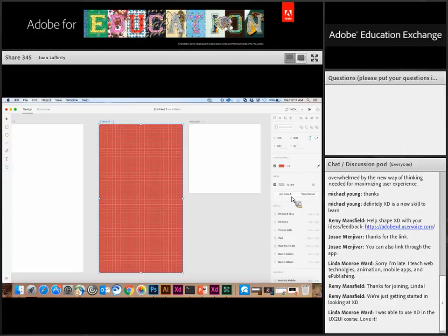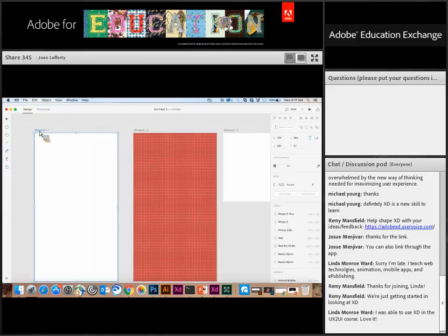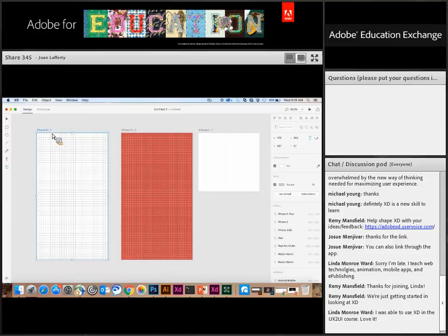And then you can create a new default. So if 12 pixels is actually the default you're going to use, you can say make this default. Then as you apply it to a different artboard, you can say to use the default, and it's using the default that you created earlier. That is just a brief introduction into using our artboards in design mode. We're going to start out here in design mode, and then we'll move on to prototyping and then sharing and export.